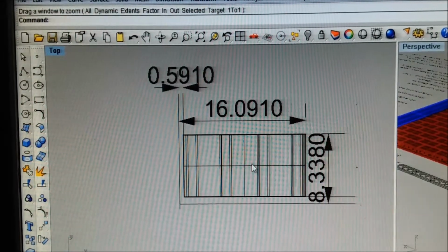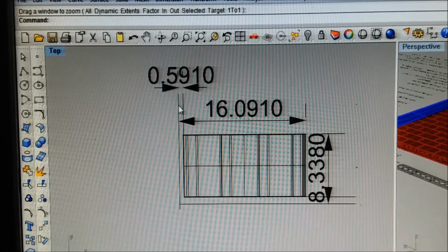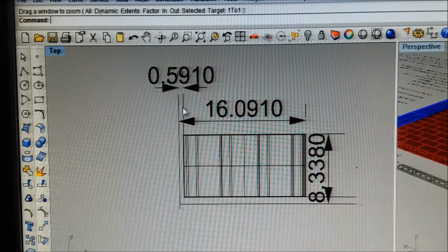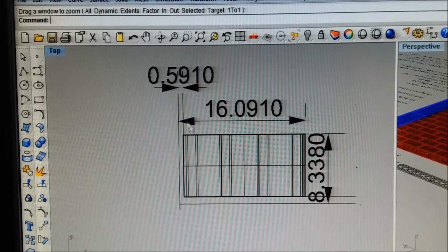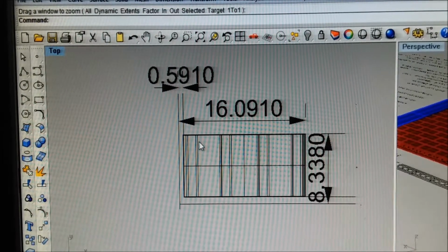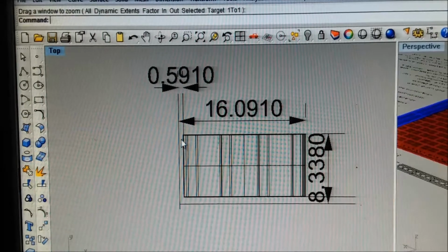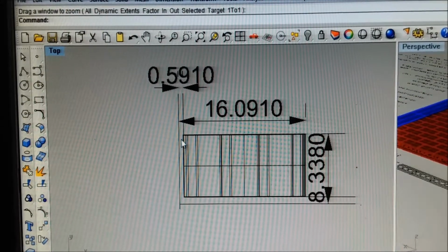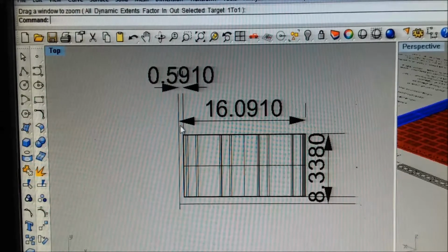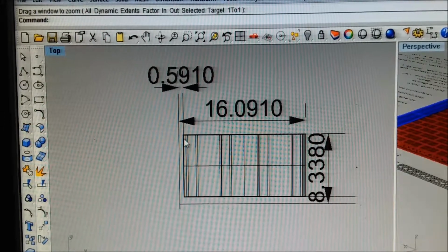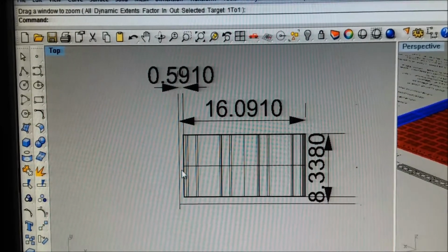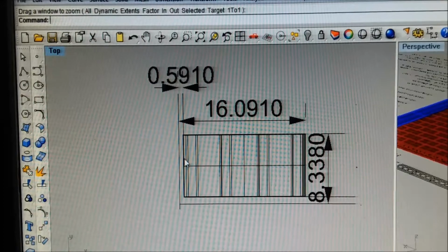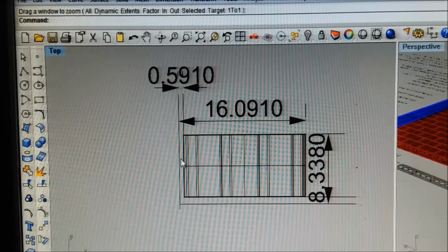Looking at our block from the side, this is the end joint. Most blocks are pretty much pushed up tight, but there's blocks that are just pieces of blocks stuck in, and there's actually supposed to be a head joint. The better builders will leave a space, and then they throw mortar in from the top into these two half cavities, and the render fills the rest. So if you put your blocks up the way you really should be putting them up, there'll be an actual head joint.